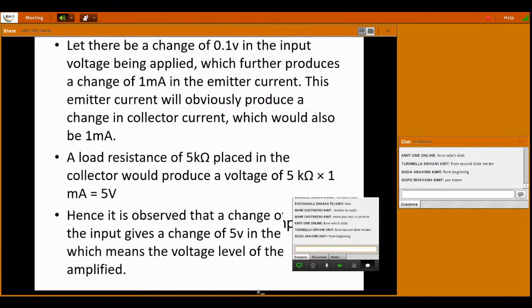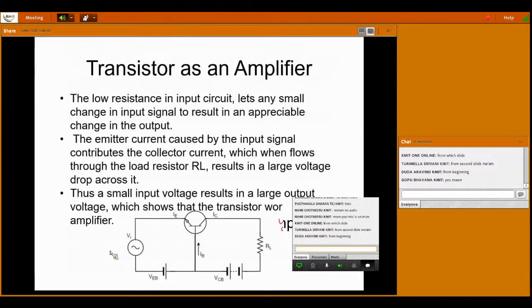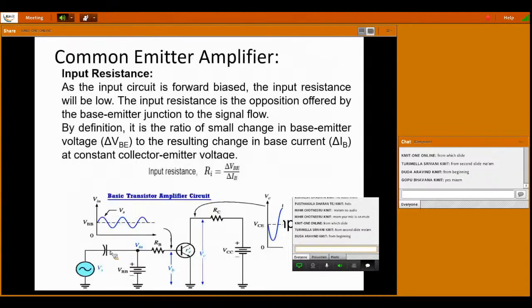Right. Next slide will be our transistor. So CV is over. We'll move to our CE amplifier. Now in the CE amplifier, like your CB, we connected the DC signals at the input junction and output junction, which forward biases the input junction with VBB, and reverse biases your output junction by the magnitude of VCC.